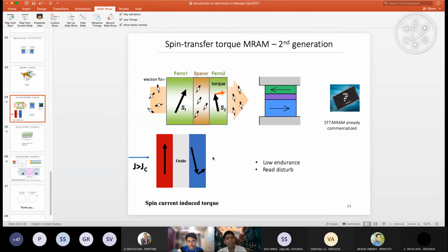The idea is not to build a complete thing out of only spintronics. In spintronic MRAM also, as I told, you need transistors, so you cannot live without silicon. Spintronic is the main storage element, but to access that bit you need a read transistor and a write transistor. So don't think that when I say spintronic devices it will be a complete magnet, no current or anything, no silicon. It's always a combination of things.